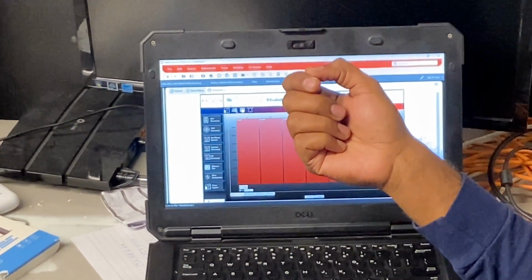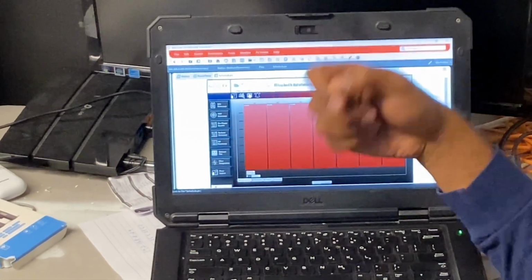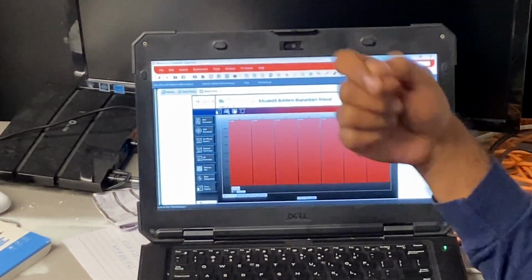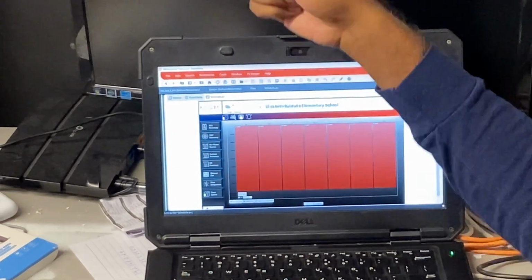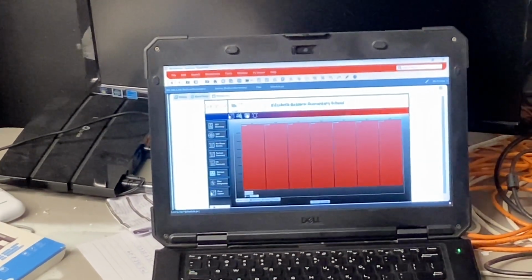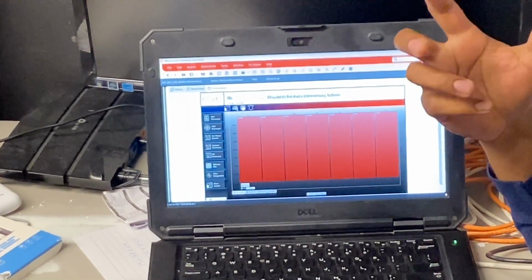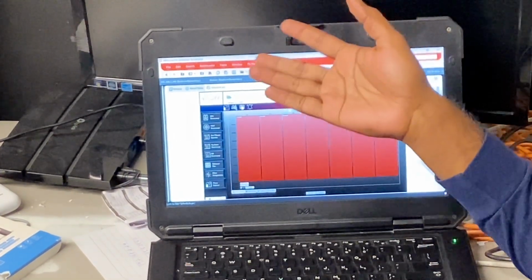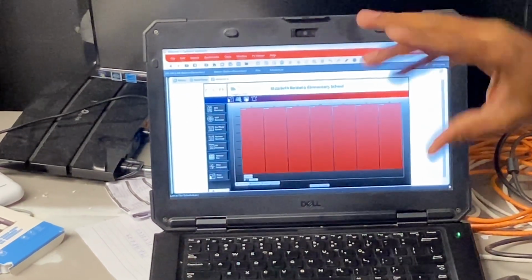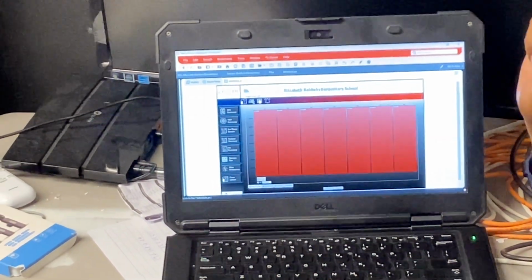Okay. So if they ask for 10% local occupancy override, then I will make my unit occupied. For example, if I have 20 and two of the VAVs are occupied, then I will put the unit to occupied, based on the sequence.